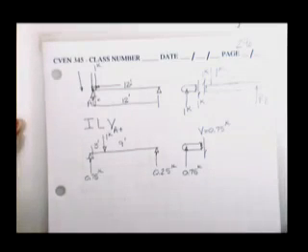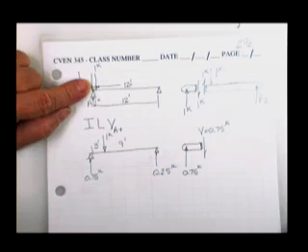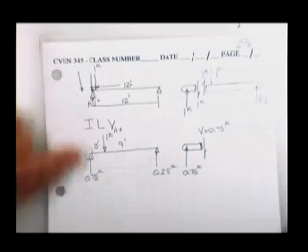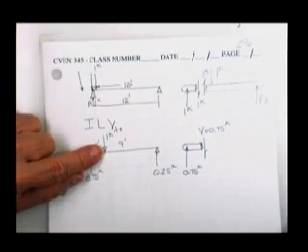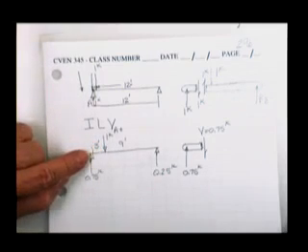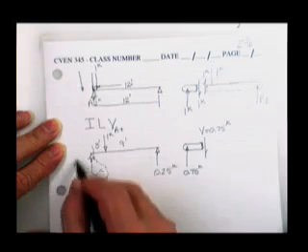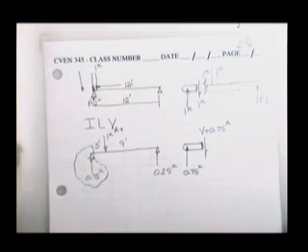I have 2 points on the influence line. Number 1, when the load is pretty close to the left end, but still to the right of the cut face, how does it influence the shear at that point? Number 2, when the load moves to the 3-foot mark, how much influence does it have on the shear slightly to the right of A?